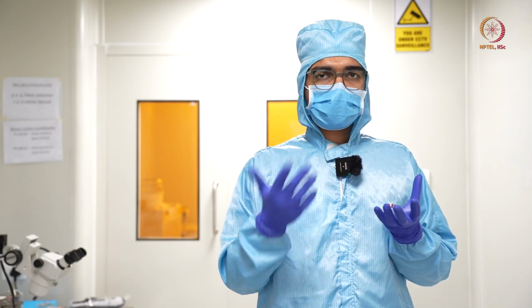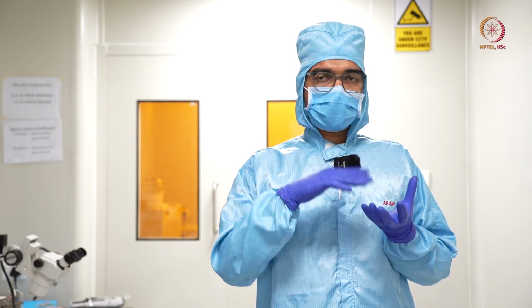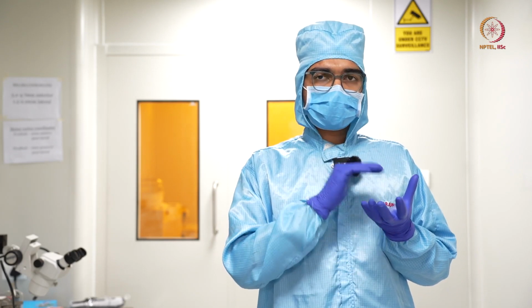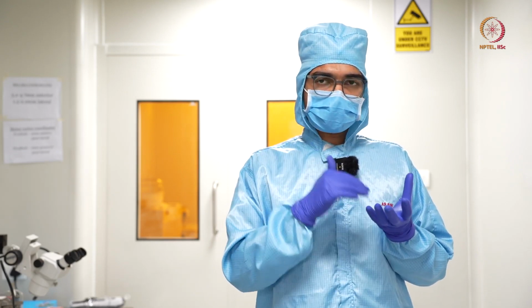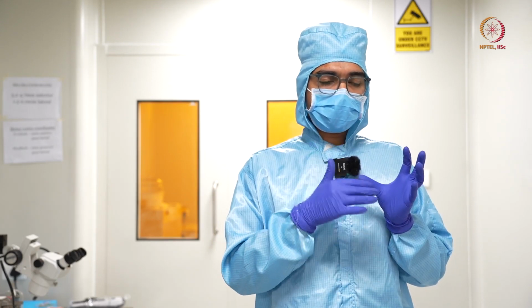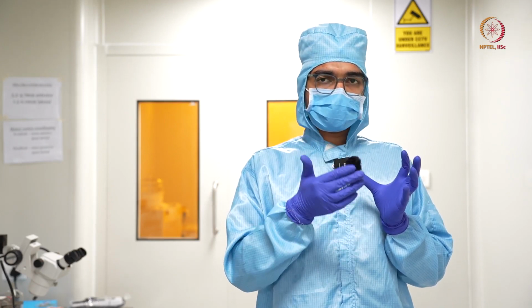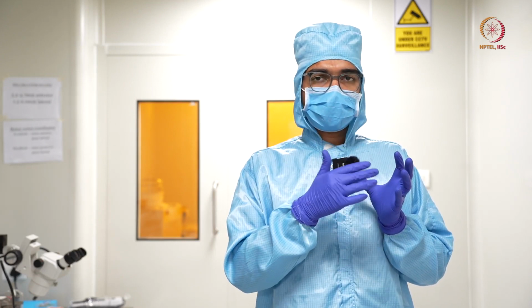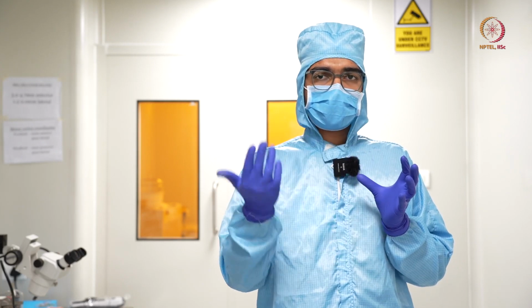Another alternative approach is to have the substrate, do lithography first, right, and transfer the pattern, followed by deposition of metal. Now what happens in this case is that when we transfer the pattern before metal deposition, the patterns will be designed such that the openings will be there where the metal can get deposited, which forms the electrode later on.